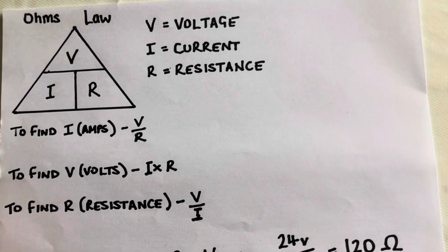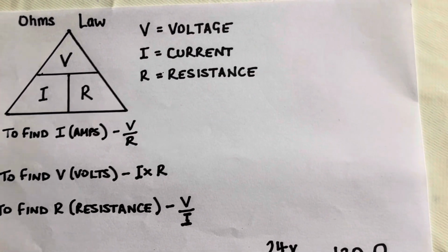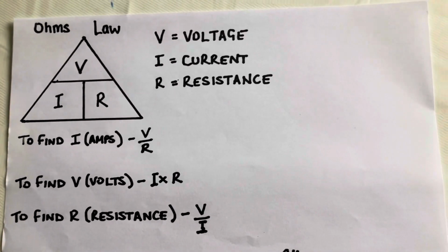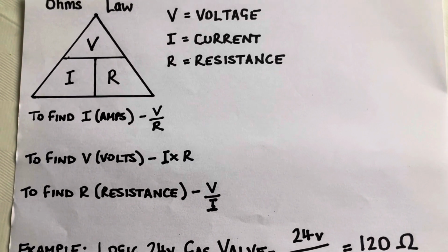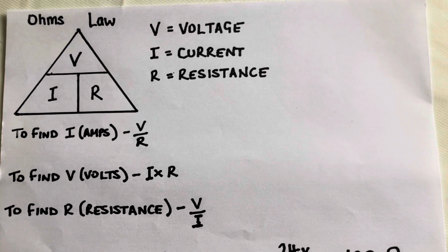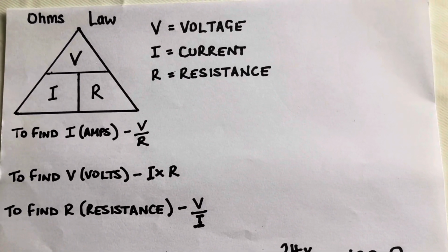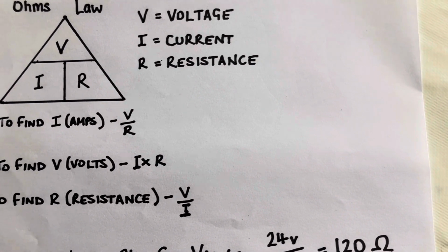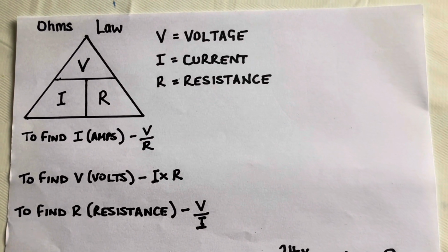I'm going to show you how to do some dead testing, not just on the components, on the harnesses as well, because you want to be checking the insulation quality of the harnesses. It's useful for checking them, especially over time when your product's been used and it's had heat from the boiler or possibly water damage on the harnesses, and it can have an effect on the operation of the cables. So like I said, people normally go for the parts, but it's not always the part.